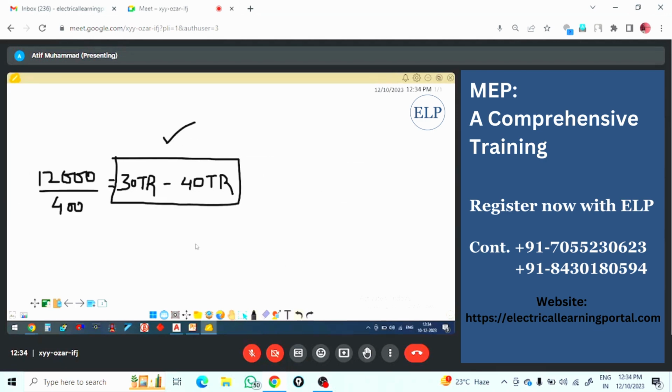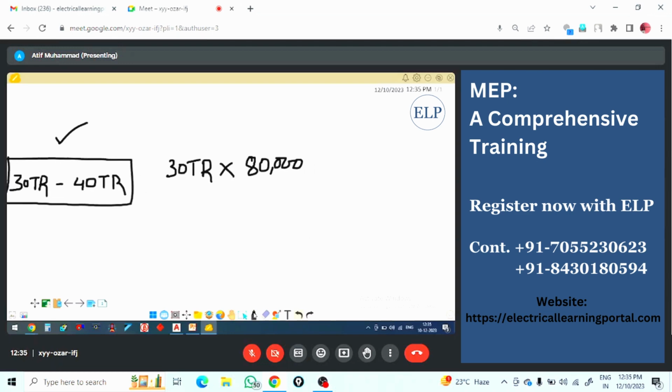And approximately, if you are going with a chiller system, suppose a 30 TR machine, then for costing, 1 TR will go, I'm not remembering exactly, but you can say 80,000 rupees. This is the rough calculation actually. 80,000 into 30 TR, so 1 TR is 80,000. This is in INR, I'm telling here. If you multiply this, it will become 24 lakh. Okay, this is the basic cost you are going to get.